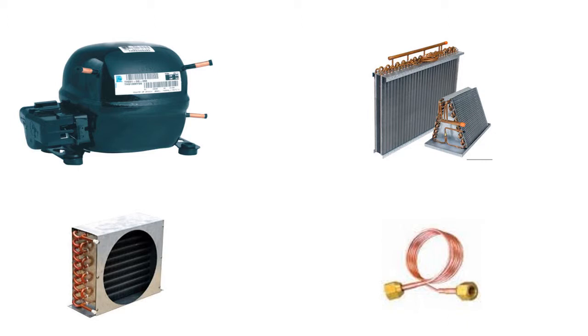The purpose of the condensing coil is to reject the heat that the refrigerant has absorbed. If you notice, the condensing and evaporator coil pretty much look exactly the same. When you are looking at a system and you want to know which is which, just remember that the evaporator is in the space being cooled and the condenser is placed somewhere outside the space. Also, the condensing coil is usually enclosed with the compressor.